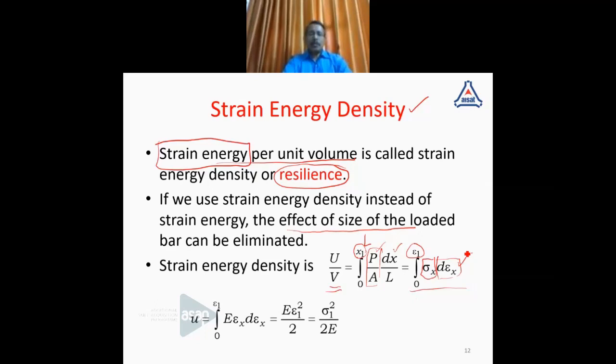And you need not worry about the integrals. Only in the derivation of these expressions do we have to use the integrals. Otherwise, we need not go for any such things. So here, we are using the small u as a notation for strain energy density. So the same expression, by replacing sigma x by E into epsilon x, is from Hooke's law.